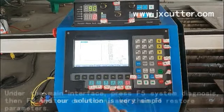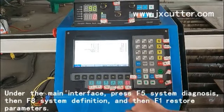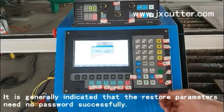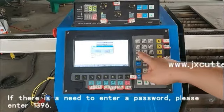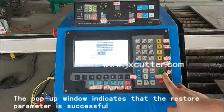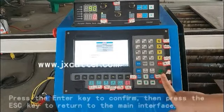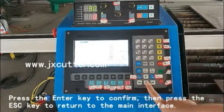Under the main interface, press F5 System Diagnosis, then F8 System Definition, and then F1 Restore Parameters. It is generally indicated that restoring parameters needs no password. If there is a need to enter a password, please enter 1396. The pop-up window indicates that the restore parameter is successful. Press the Enter key to confirm, then press the ESC key to return to the main interface.